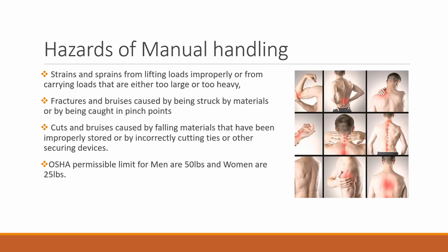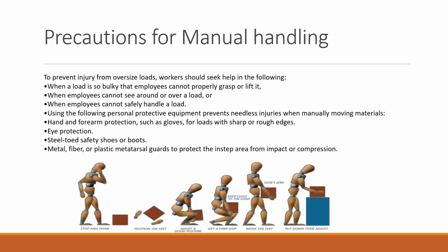When we are going to perform manual handling, especially lifting, we need to have one thing very clear in our mind: the lifting plan. It is not necessary to have it in written form, but when we are dealing with cranes and heavy lifting, the lifting plan becomes mandatory as a document.